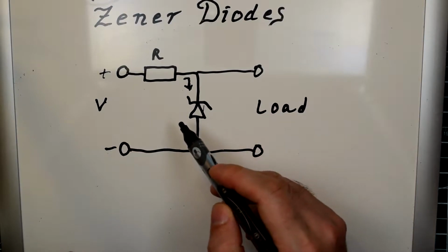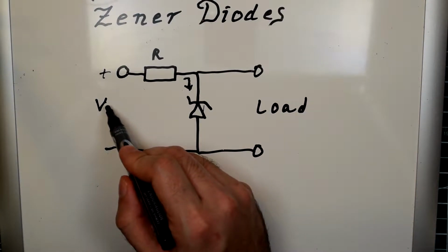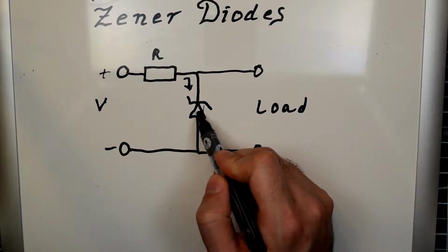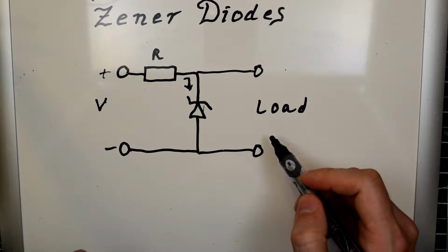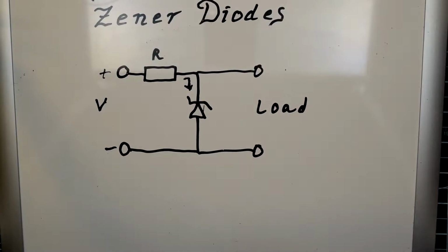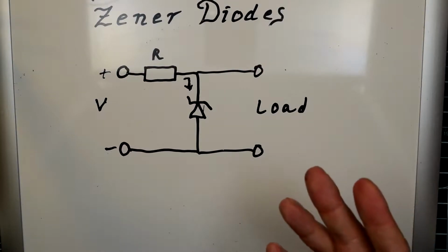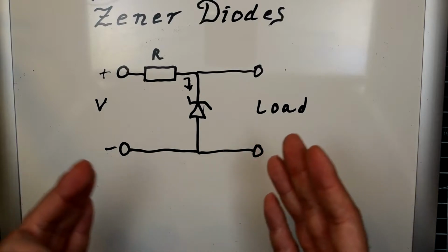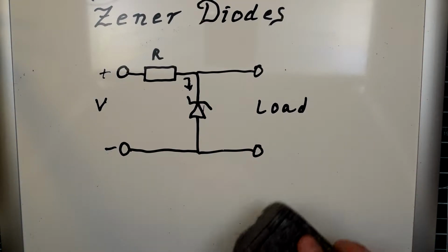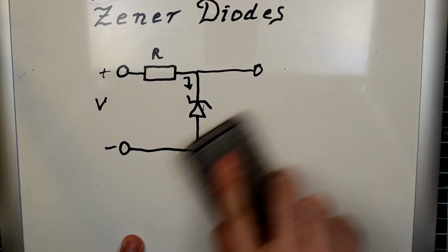The other disadvantage to this is that if your voltage here is less than the Zener voltage, that voltage will appear here. So it better not be a circuit that will malfunction or be damaged. But, well, I guess it couldn't really be damaged by having too little voltage, but it may misbehave. So that's one use for a Zener diode.